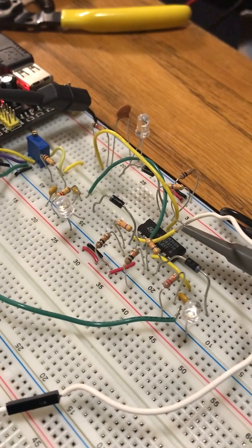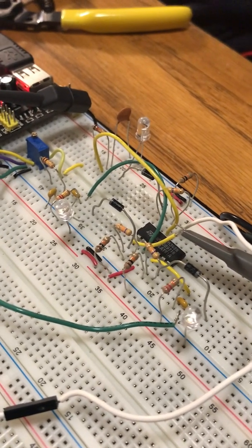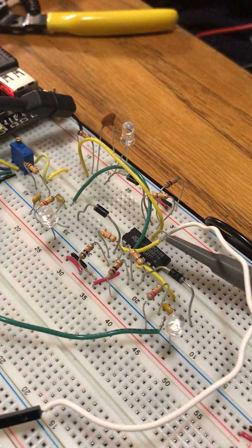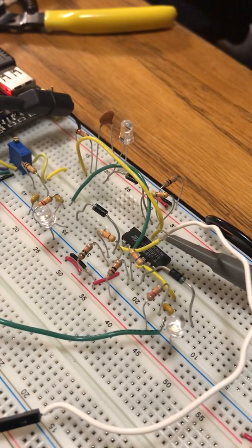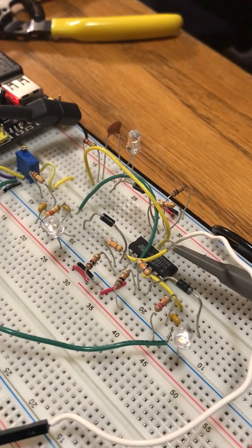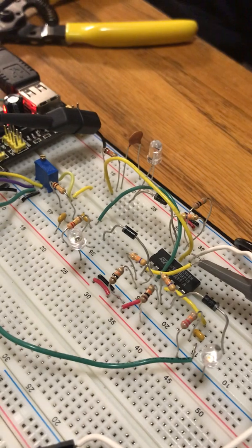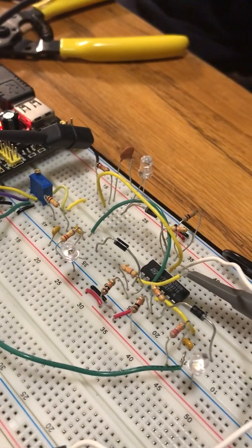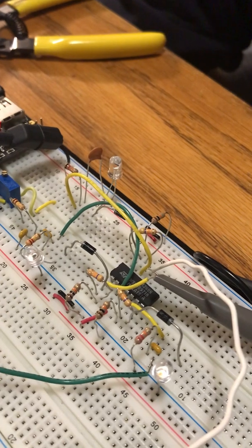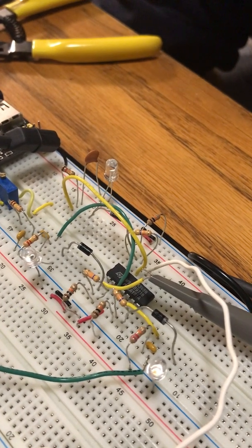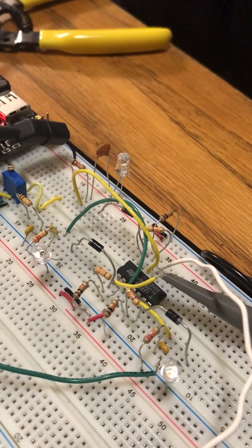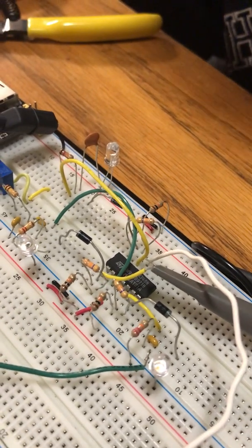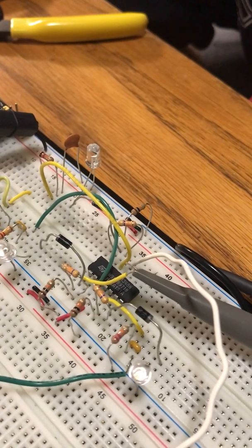So the cutoff frequency for the low pass is around 125 hertz. So 100 hertz is in the pass band, and then it is not in the pass band as the frequency gets higher. The band pass is basically made out of a low pass filter and a high pass filter connected in series. For the high pass filter, the cutoff is at around 750 hertz, and for the low pass filter, the cutoff is around 1.25 kilohertz. So the pass band is basically between 750 hertz and 1.25 kilohertz.